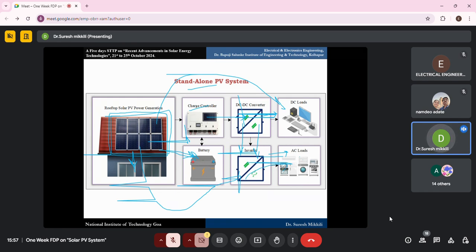If the DC-DC converter is not there, the entire energy required by the DC load has to be converted directly, and the amount required for AC loads will be given to the inverter and connected to AC loads. Here the burden on the PV panels will increase, and the size of the PV panels will increase to meet the criteria.